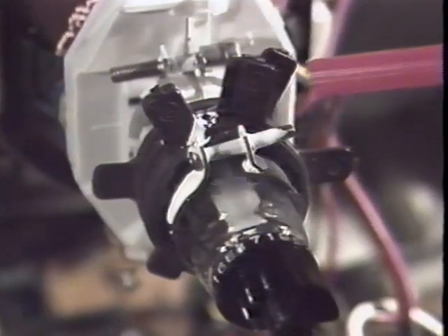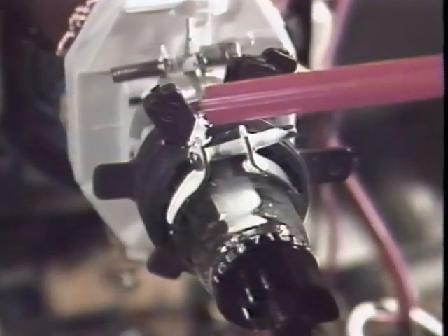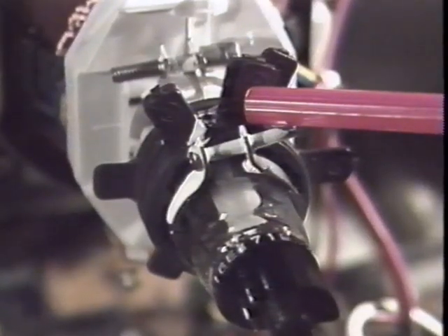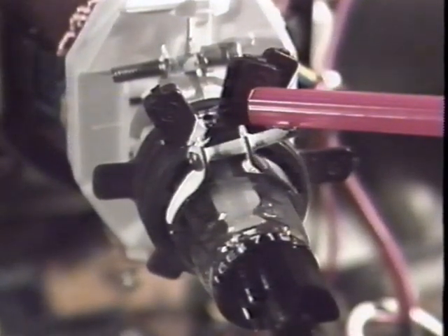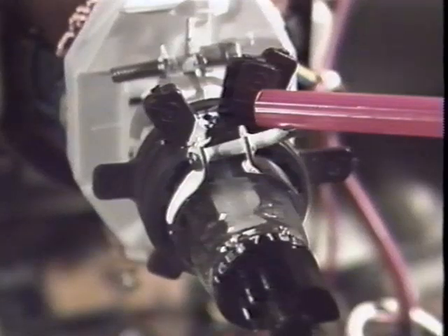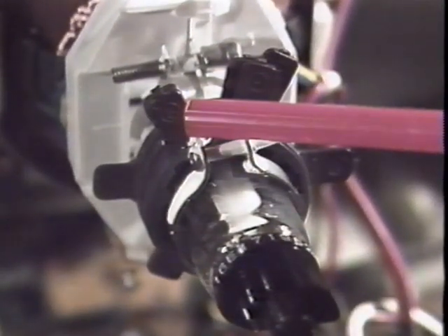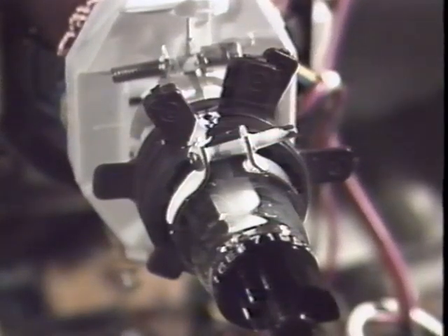To make this adjustment, you move the other two sets of magnets behind the yoke. One of these sets of magnets is labeled with the number 4. These are the 4-pole magnets, and they bring the red and blue beams together to produce magenta. The 6-pole magnets are labeled with a 6 and converge the green beam with the red and blue.